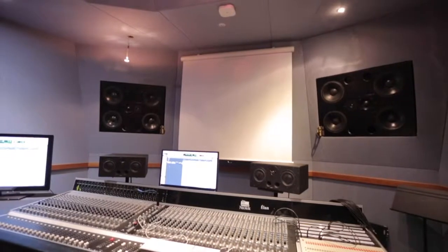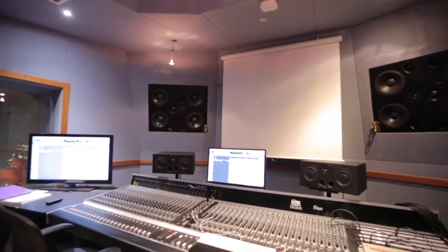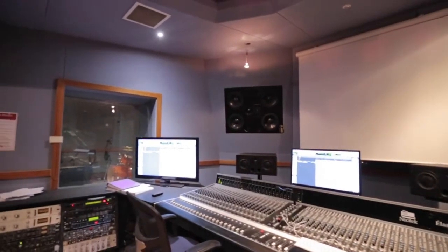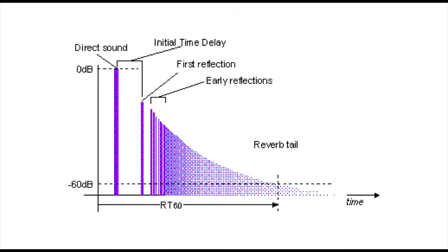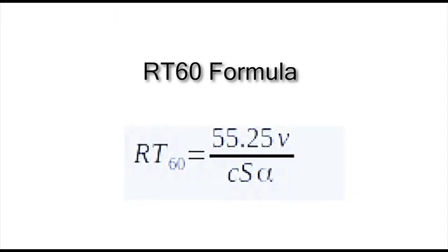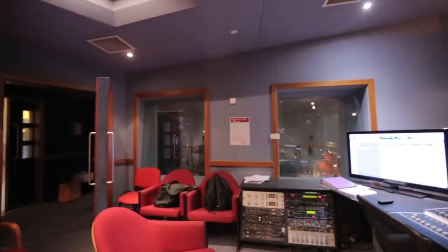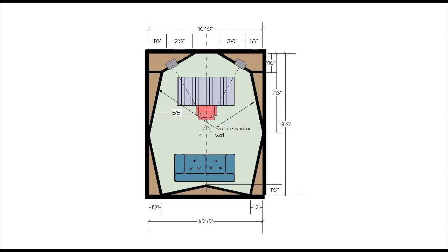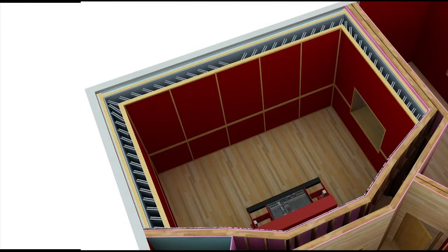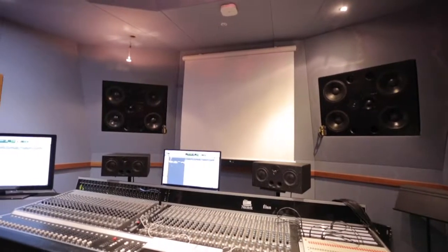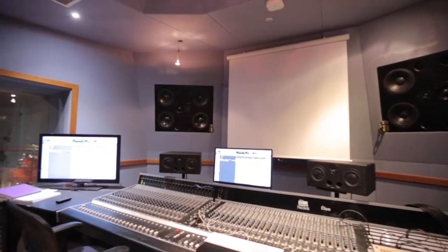Frequency response in a recording studio is very crucial, especially in the listening and mixing room. These spaces should be treated for a lower RT60, meaning the length of time it takes for a signal to drop by 60 dB. For a studio control room, it should be between 0.2 and 0.5 seconds. To get better results, recording studios should have no parallel walls, and the walls should be treated with absorbent materials, from the floor to the ceiling.